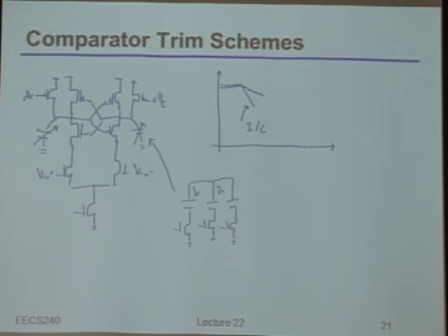So for example, 1x, 2x, 4x, and so on and so forth. And you'd basically tie them to some digital switches. So let's say D0, D1, D2, etc. And of course this is the node I'd actually connect on that side over there. By turning these switches on or off, I'm basically programming how many of those capacitors really show up and load the output.